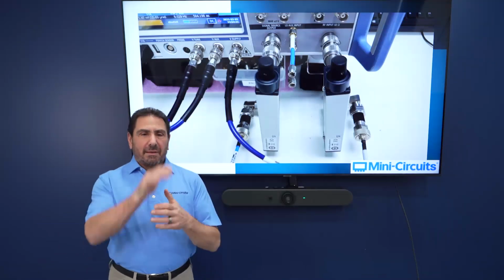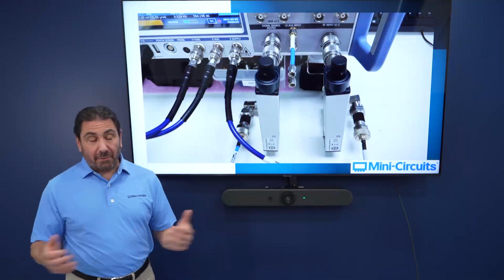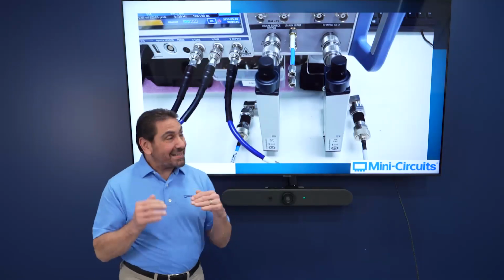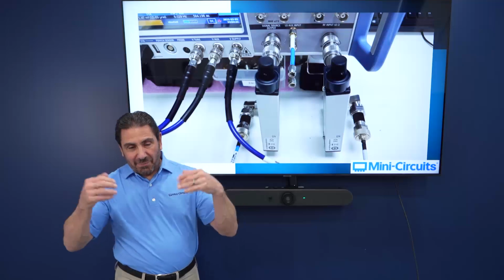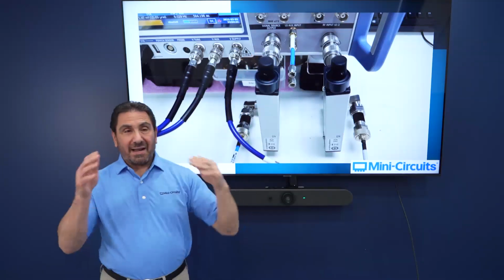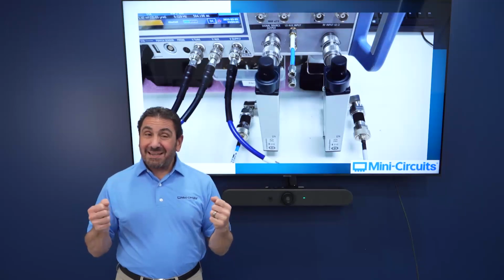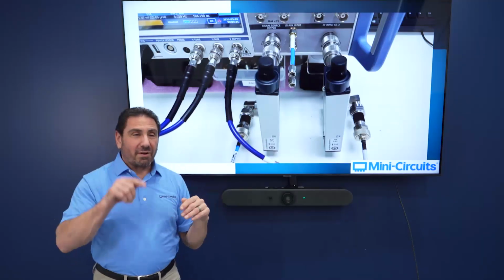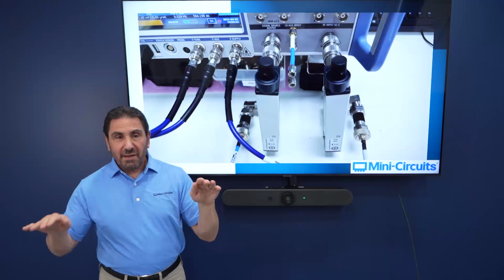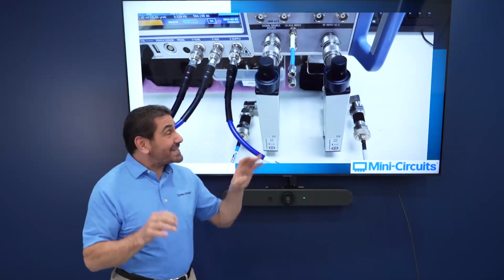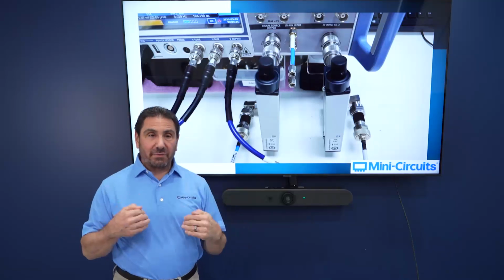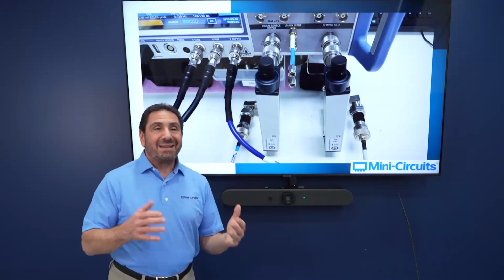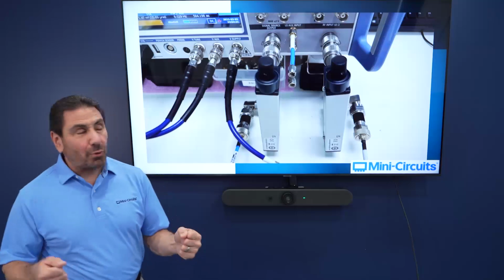And then we examine the additive phase noise from our instrument noise floor. If we like it, good, we move on to the next carrier frequency. If not, there's a dependency between additive phase noise that we measure in the through path and the signal power coming out of the analyzer. So if we don't like what we see, we lower that power a little bit. Lower the power, run it again. Lower the power, run it again. That's good. Eventually you will get a trace that you're happy with. You record that. That's the highest I can set this to and achieve acceptable results. If we can do it at plus 13, fine. If not, we lower it. It may impact your input dynamic range, but we're doing that to favor the additive phase noise performance or the noise floor of the system.